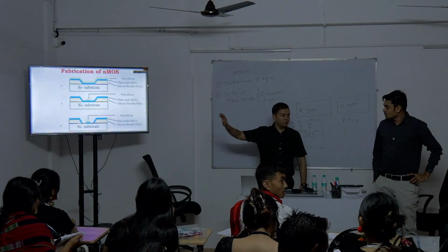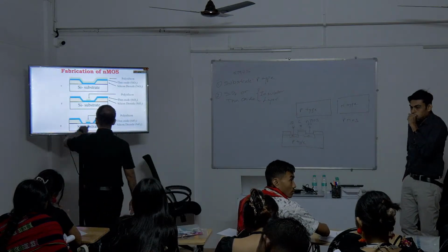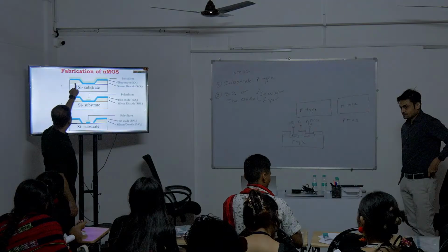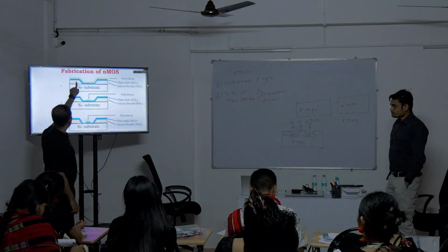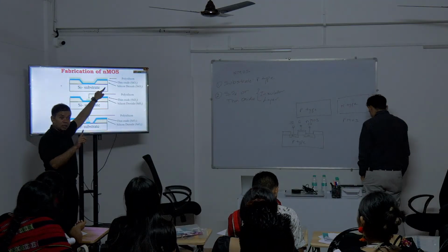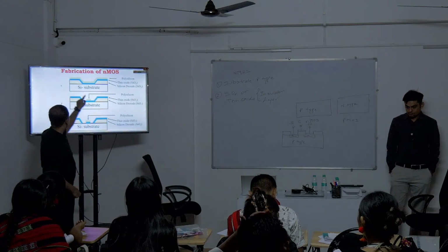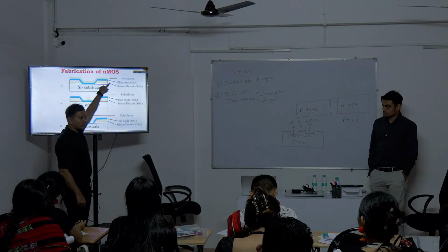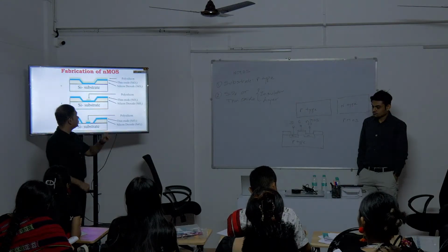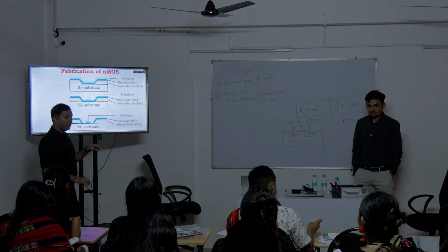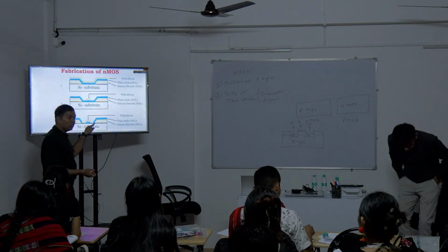So can you now try to imagine that if I have different layers now, right? So we started with a silicon substrate, then we had this one, silicon dioxide, which was complete. Then we just have got this one first. Now, because I need this layer over here, what should I do? I should put this layer first. And then again I need to go for the photolithography, so that wherever I need this layer, only that should be there. From the rest of the portion, I need to remove that blue layer.